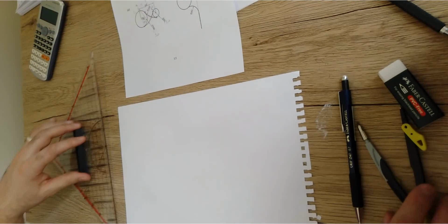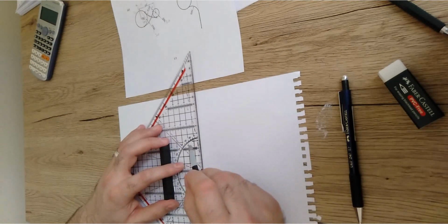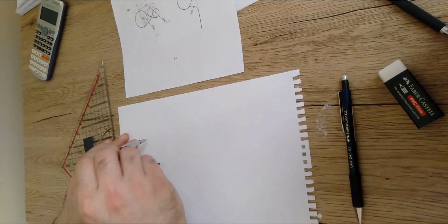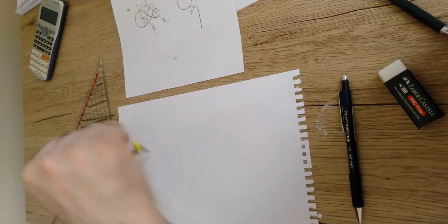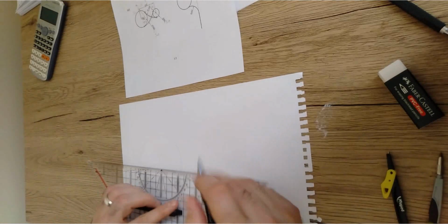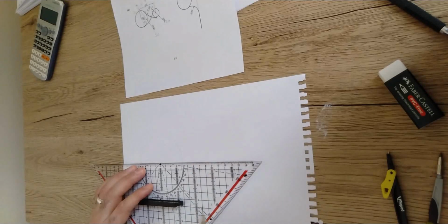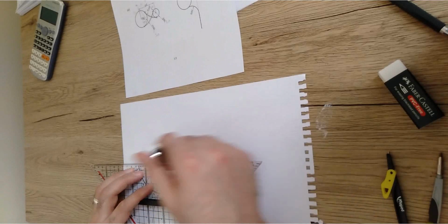Then you can look at a point and draw a vertical line. So this is what I'm gonna do. In the beginning, I'm just gonna open the compass by the 40 millimeter radius. Then from any point, I'm just gonna draw this circle. This should be the big circle, no problem. Then from this center point, I'm gonna draw a line. I'm just gonna make sure that it is parallel to the edges of the drawing sheet. That is horizontal in this direction.